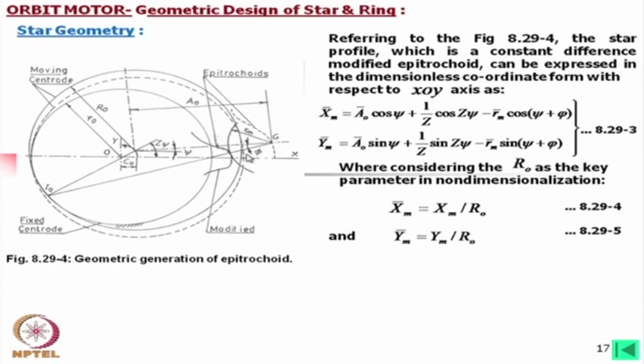Now, for this profile you will find that the generating point will move. That means, when you are generating this curve, it can move in this direction and in this direction by a maximum of this angle, which is called the leaning angle. Now, to find the equation of this point, we simply take this radius in this inward direction, so a minus sign is there, and the angle is this angle plus this angle. Geometrically you can easily find this out.